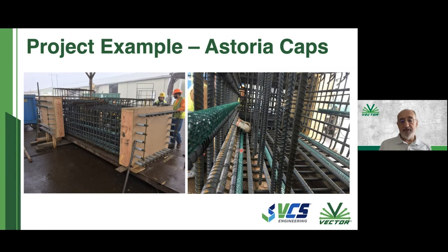Again, these are caps, but in this case, because you have a lot of steel in that direction, they chose to use the DAS anode, which are long rods, or now actually long prisms of galvanic anode, and you obviously get better distribution and much higher current as well, because it's a much larger anode.